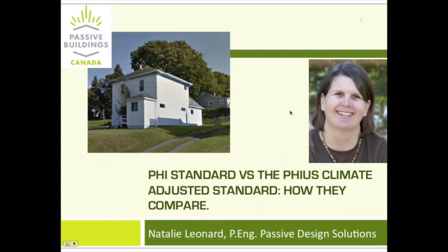So PHIUS separated that out and made an adjusted sensible recovery, and also collected the watts per CFM or CFM per watt, I can't remember which order the units go in, which are the two numbers you need for energy modeling in both PHPP and WUFI Passive. So that sheet's available. It's publicly published on PHIUS's website under their resources.